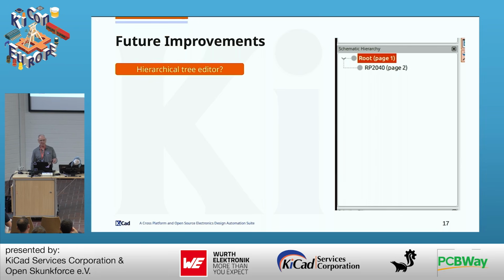It might be interesting to flesh out the hierarchical tree viewer and turn it into an editor where under each instance you get the schematic and the things that you can change. So in there you could add a new variant and change from the default. Let's say you wanted a variant of a 1K resistor and you change the variant to a 10K or whatever. So you can actually see where in the schematic that gets changed.